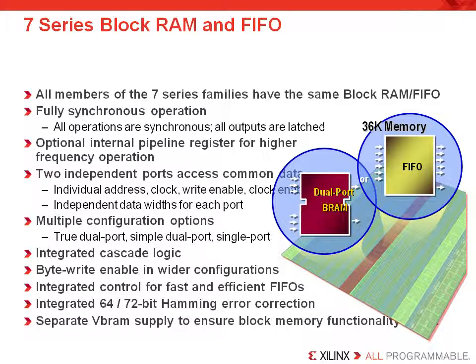The block RAMs also have 2 independent ports, so each port can have different read and write port widths, and each port can have its own clock and different read and write aspect ratios. The block RAMs also include a configurable aspect ratio functionality, which allows each block RAM port to have its own customizable width. This helps the memory lend itself to more applications and ensures efficient use of the memory space.